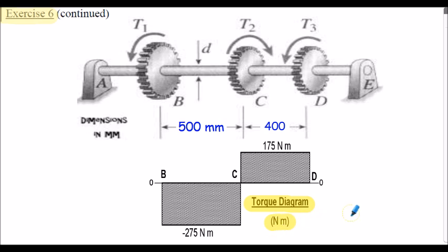This is slightly analogous to the shear force diagram that we often draw when considering shear forces applied to beams in bending. If you consider the torques here analogous to the shear forces, in a shear force diagram associated with beams, we account for the direction of the shear. We have a positive notation for shear defined, and we draw our shear forces from left to right across the beam in accordance with that notation. The same approach applies here.